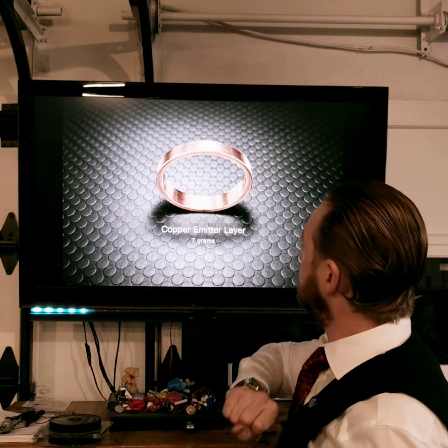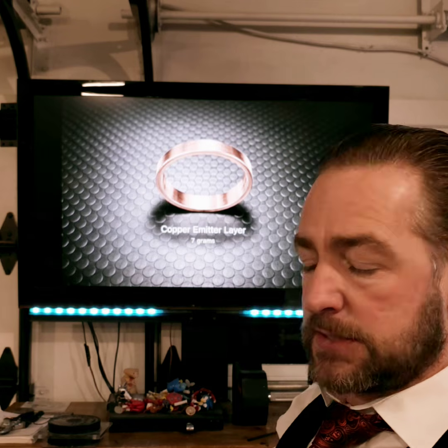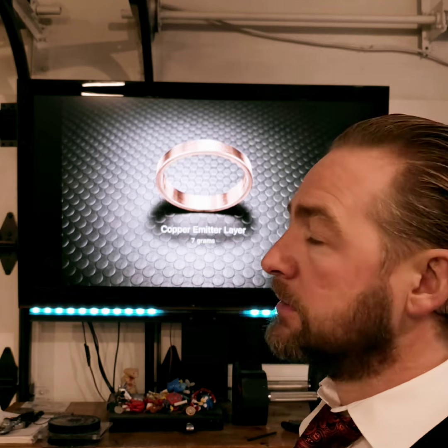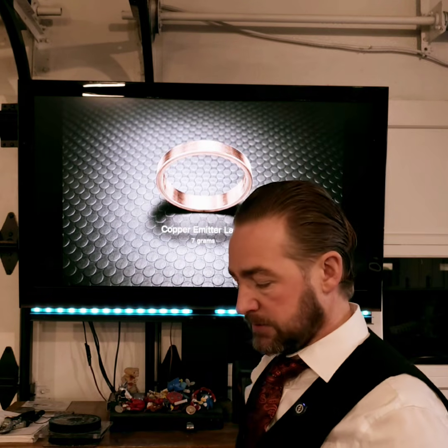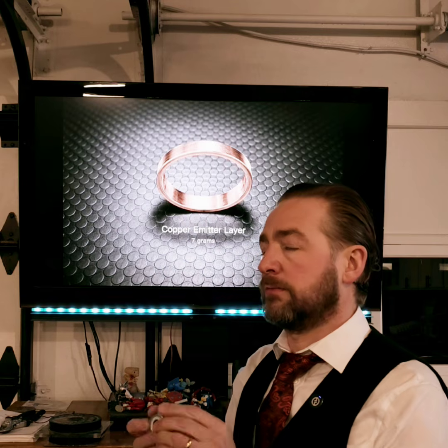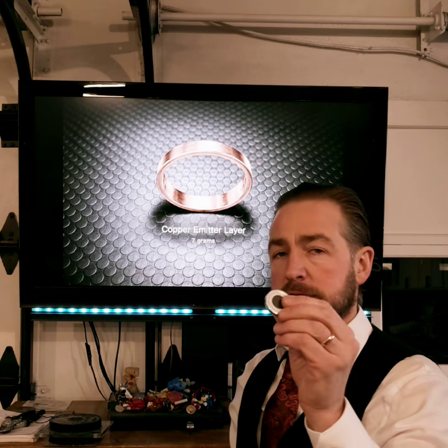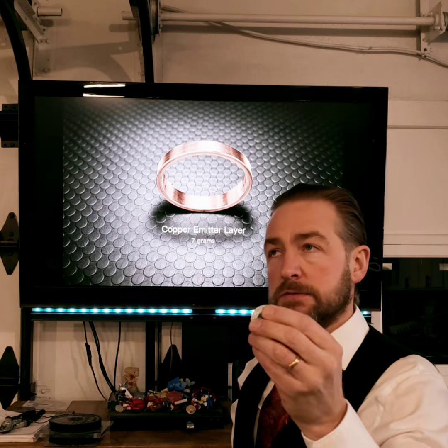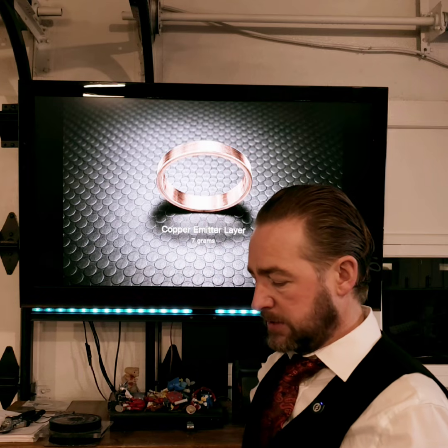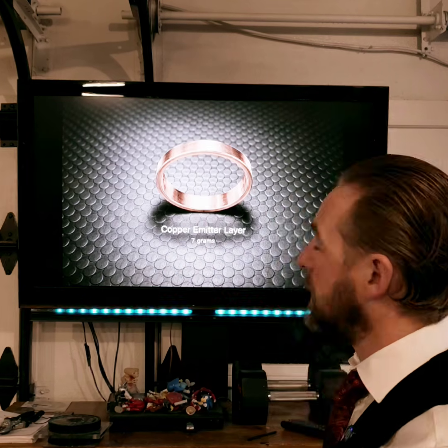The copper band, same as the stator, when in relation to a magnetic field, creates eddy currents. Now, something interesting I found: when the rollers rotate as bare magnets, the eddy current effect is greatly enhanced. But when you have these copper sleeves on, it seems to have kind of a, not a nullifying, but a washing out effect.